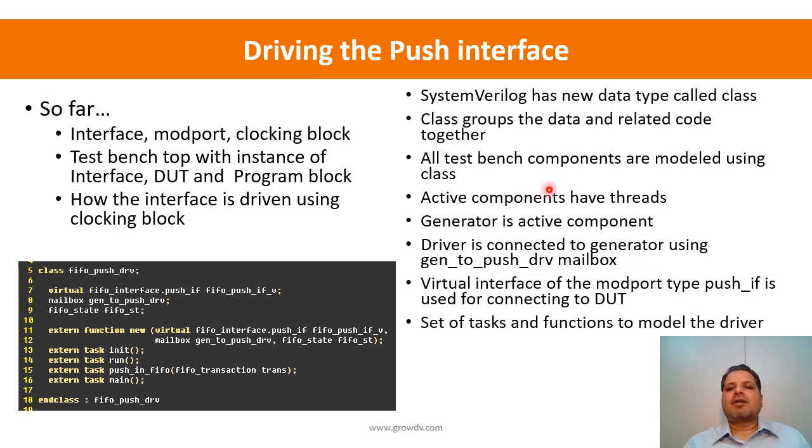And what the push driver does is it takes the virtual interface of the FIFO interface that we have created, virtual because we are doing it in classes, which are dynamic in nature. So it takes the virtual interface and it drives it out. It drives the information that it has received through the FIFO transaction on the virtual interface with the help of a set of tasks or functions, right? So that is what it is doing.